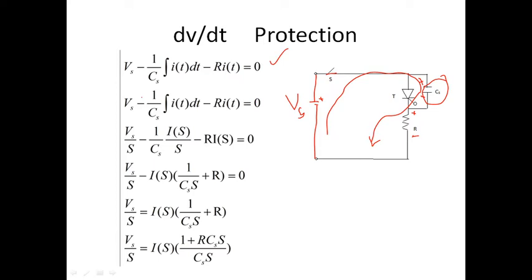So then you just write like this. Now to this time domain equation I am applying the Laplace transform. Then I will write the equation in the S domain. Laplace transform of 1 is 1 by S, correct? We learned it, so Vs by S. Laplace transform of I of t is I of S. Integration is there. Laplace transform of integration of f of t is F of s by s.